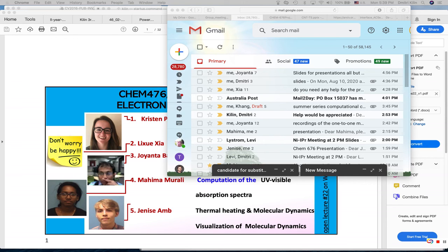And then there are examples of a couple of POTCARs. We can find some very important information in the POTCAR. The first one is the number of valence electrons, and we can see that the copper valence electron number in this POTCAR is 11. And the atomic mass of copper is about 63.